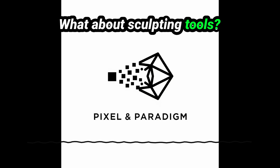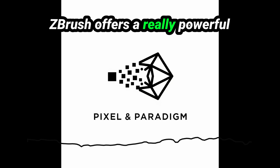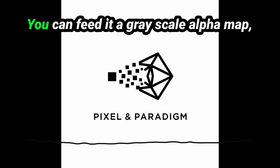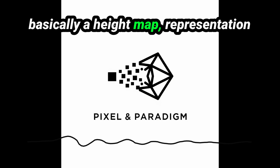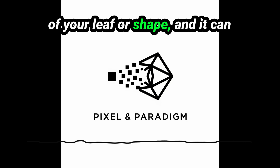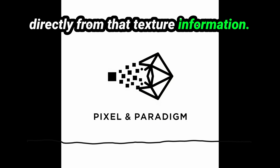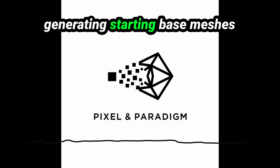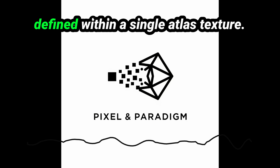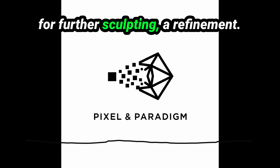What about sculpting tools? Can someone like ZBrush help here? Oh yeah, ZBrush offers a really powerful feature called Make 3D. You can feed it a grayscale alpha map, basically a height map representation of your leaf or shape, and it can quickly generate a base 3D mesh directly from that texture information. This is particularly useful for rapidly generating starting base meshes for many different leaf shapes defined within a single atlas texture. It gives you a great starting point for further sculpting or refinement.